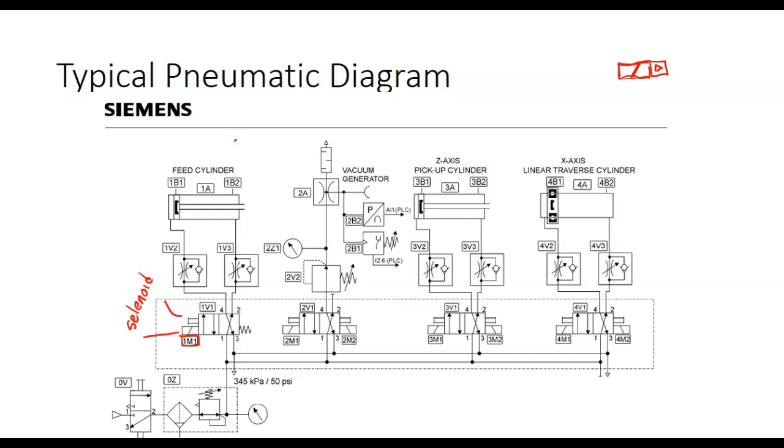So how would we nomenclature this? What would we say this valve was? A 4, two-way, solenoid operated, spring return with a manual override. And you'd have to know that just to order it, right? Makes sense.